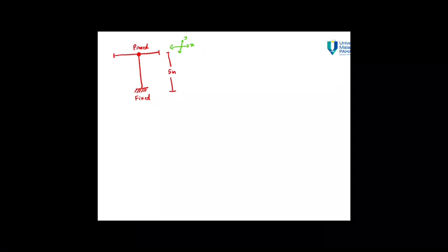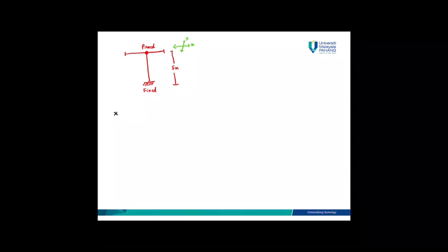To analyze a braced column, first you need to determine the effective length of the column subjected to X-axis buckling and Y-Y buckling. For X-axis buckling, in a simple word is you look from X view. Means that you look from here. For example, this is your eyes. You look from here, from X axis. If you look at from X axis, you only can see